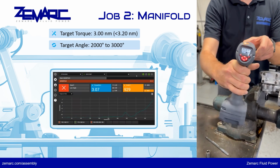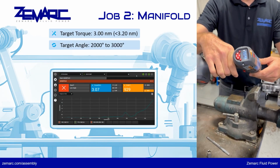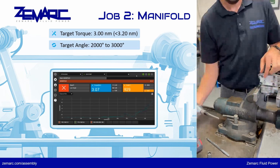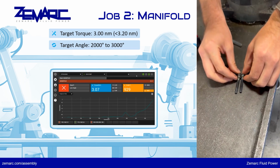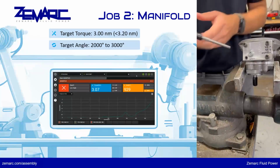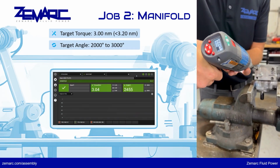And you'll notice something went wrong there on the 4th fastener. So if you look at the controller screen, you can see we met torque, but we had a low angle. So let's inspect what this means. You can now see the 4th fastener looks very similar, but it is a few millimeters short, putting it out of spec. So we'll go ahead and reinstall the correct length, and you can see this now completes the sequence.